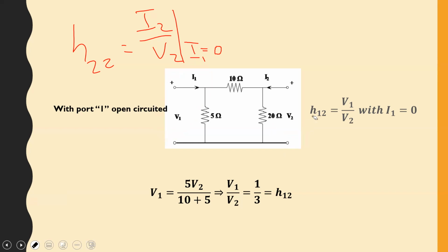If I asked you for the relationship between V1 and I1, as a matter of fact, we already did it. What did we do in finding the relationship between V1 and I1? Brian, you should have it in your notes. We open circuited port 1. Well, forget about the open circuit. How did we find a relationship between I1 and V1? We short circuited port 2.